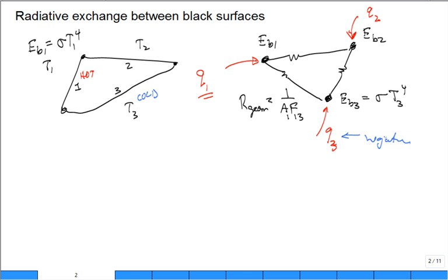And to develop the equations, you typically do an energy balance around a node. So the energy balance for each node, well, let's do it for node E_B1. What we would have is we'd have the in, and then it's traditional to write everything else is flowing out. So the rate of heat transfer in Q1 is balanced by what flows out. I'll just kind of sketch it this way. Through the resistor 1 to 2, plus what flows out through the resistor 1 to 3. Why don't we write everything coming in?